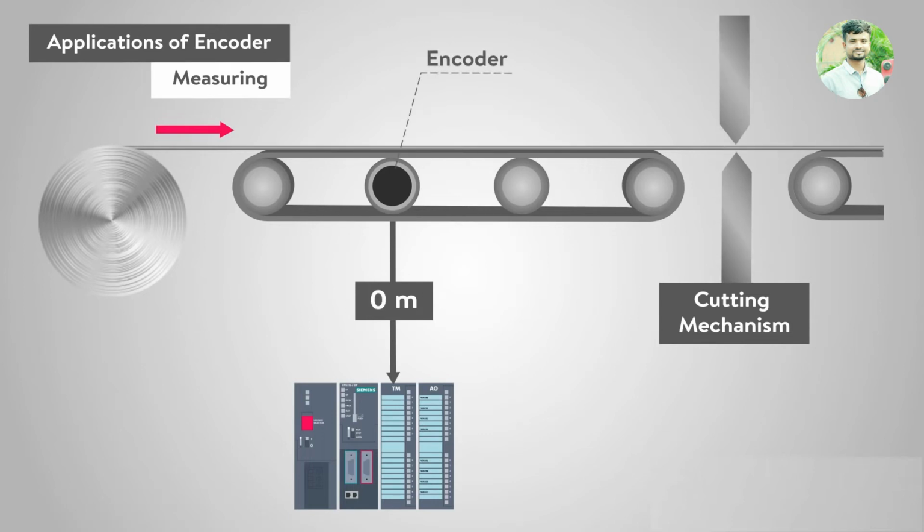An encoder attached to the conveyor and reading the material that is feeding through your cutting assembly will indicate the length of material that has been fed since the last cut. That feedback can then be used to adjust the cutting blade to sever the length required.